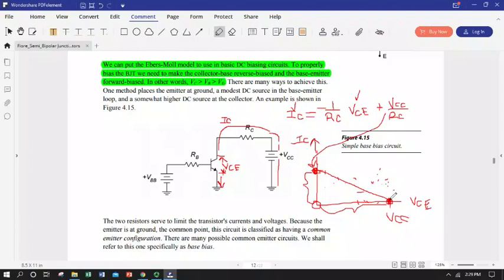So we got some more vocabulary having to do with transistor operating points, but this is the transistor and the circuit working together. The plot lines that we saw that go on a spec sheet are the transistor characteristics alone. So this is cutoff, this is saturation, and they're both dictated by really the collector emitter path and its KVL expression.